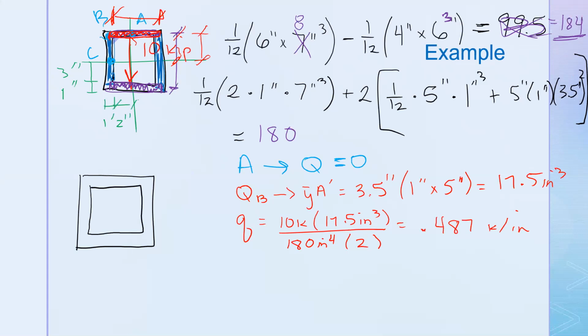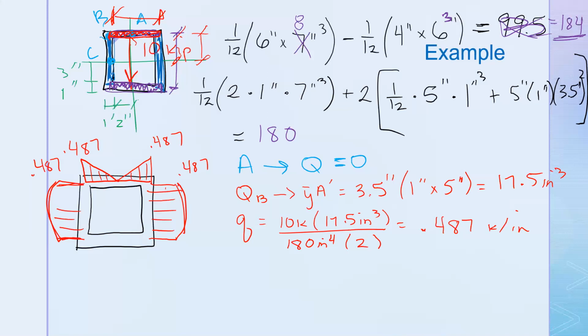And we know because we're traveling along a horizontal member it's going to be a linear distribution. Okay, and then when we get to the sides, we know it's going to be parabolic, and it's going to start at the same value. So now, when we had the I-beam, the two flanges were adding together to go into the web, but here we just have the one side continuously flowing into the next, and so these are just going to be equivalent. But we want to know that maximum value of Q. So at point C, we want to know Q.